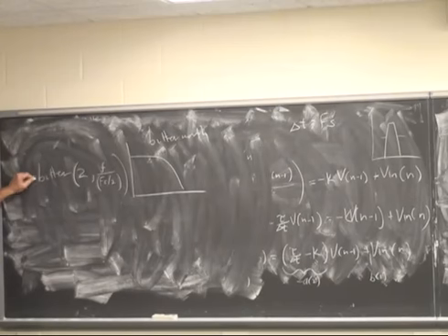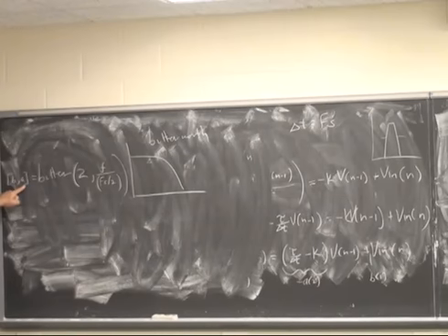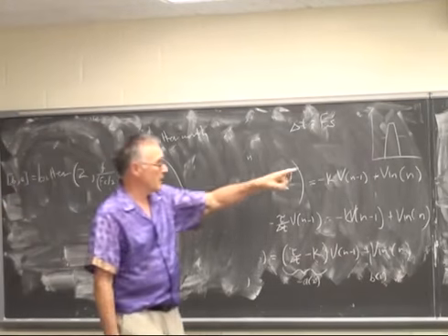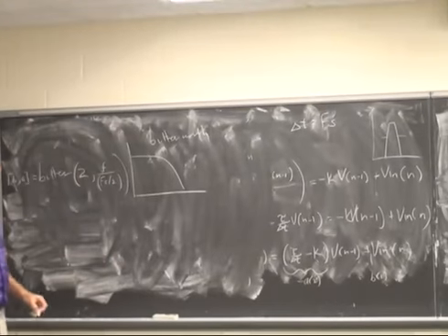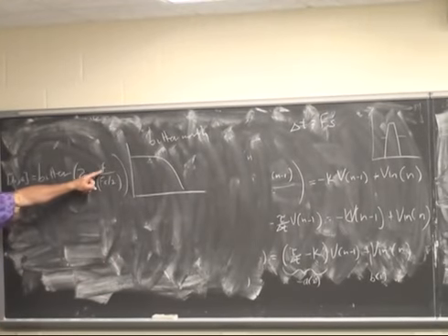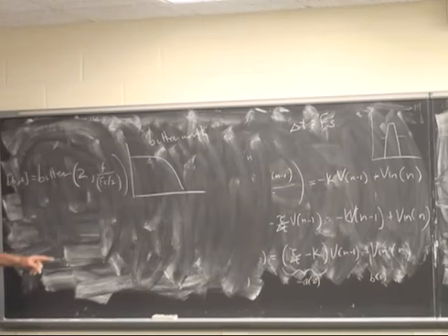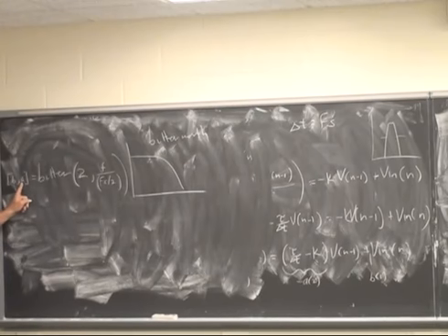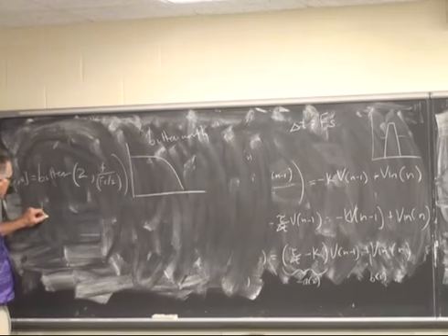This command, with the parameter b comma a here, will generate the b vector and the a vector for you. If you do this for a small f, you will find that these coefficients get quite small, that b and a become quite small. This will build a low-pass filter.